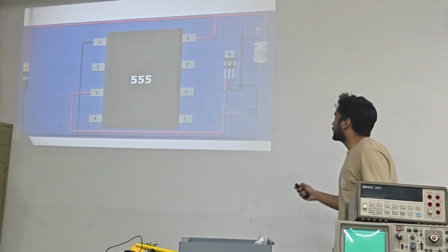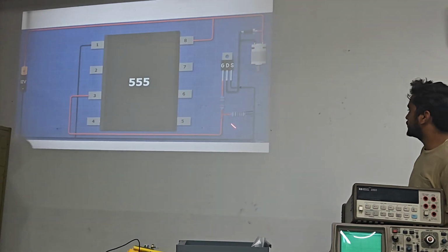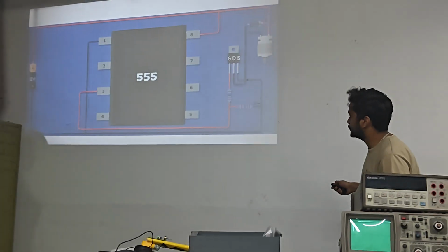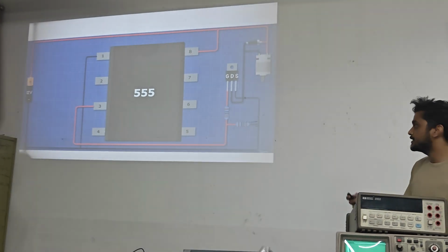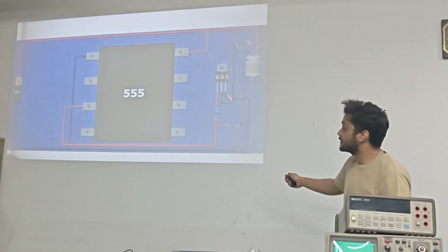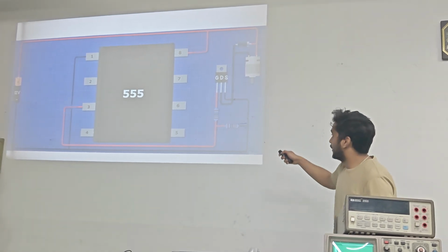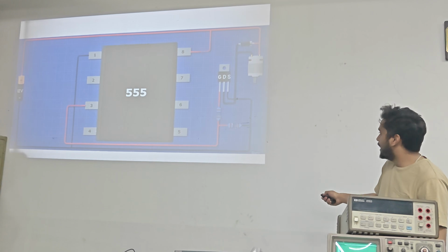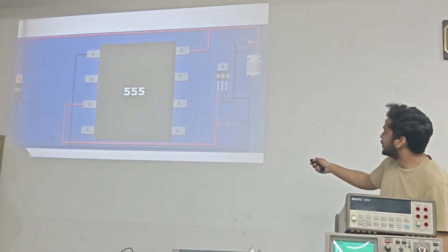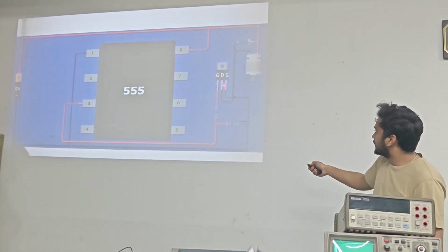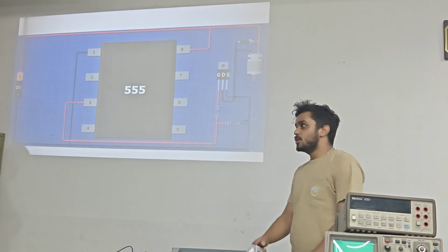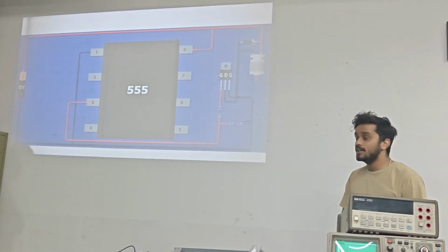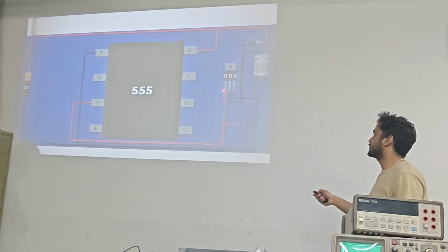Now we have added these two resistors over here. This resistor specifically we have added to protect the 555 timer IC, just in case this MOSFET malfunctions and the current comes back to the IC. And this resistor we have used to discharge the gate terminal of the MOSFET. While switching, with faster switching, some charges will be developed on the gate pin, and to discharge it safely, we have used this part.